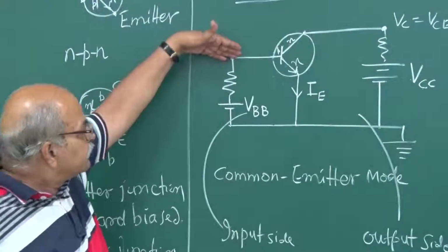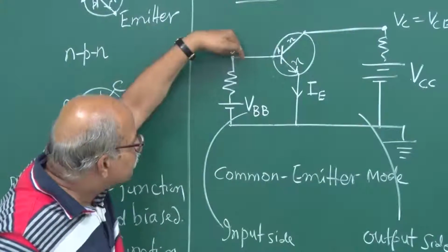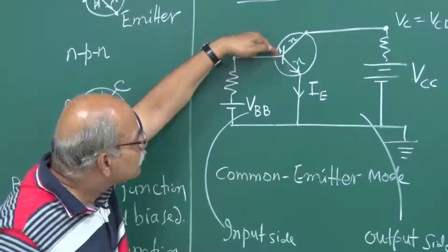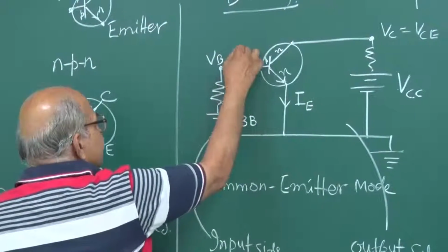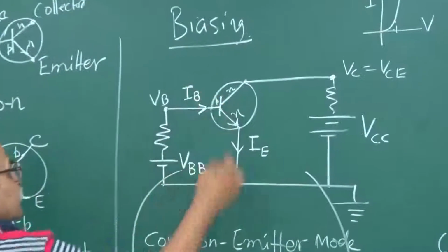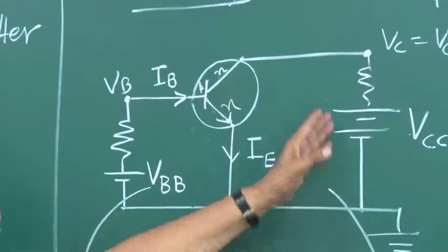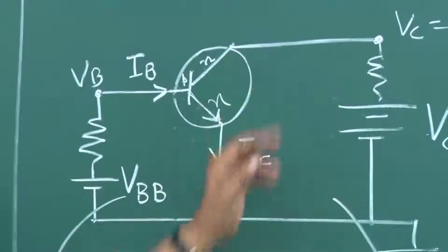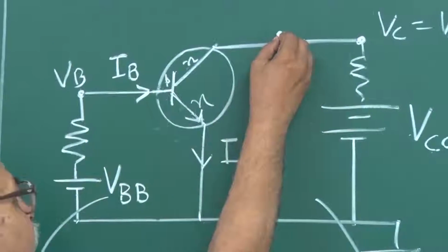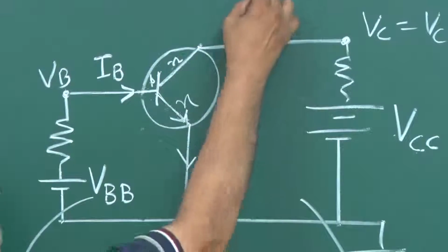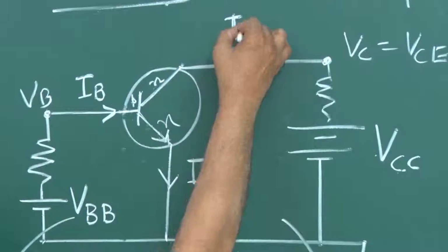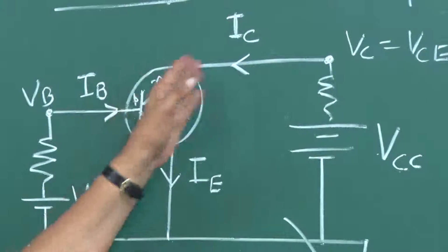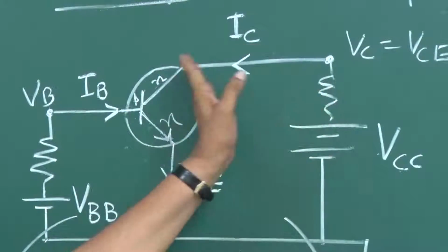And then the current should enter this PN junction, goes from P to N. So this current goes here, it enters here, this is IB. And then any current that is here in the collector, that is written as IC, and this arrow is IC. Okay, remember this is reverse biased, and then the current will be of this type.